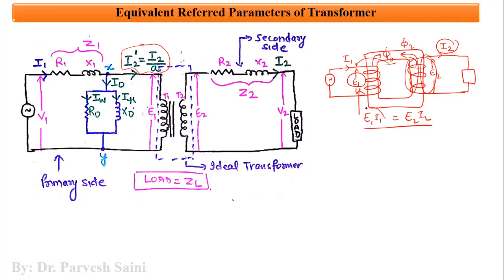So to have the same power, we need to keep the strength of the induced EMF maintained in the primary winding. To do so, when E1 reduces, V1 becomes greater than E1, to send more current to the primary winding, an additional current basically. And this additional current is, let us say, I2 dash.